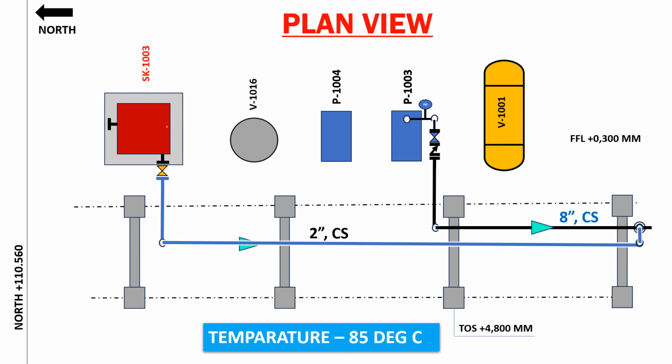The equipment is a bigger unit, so it has more weight. It is anchored and fixed. So if the line needs to expand, it only needs to expand in this direction. I will mark it over here. If the line expands in this direction, then this length will be extended up to here. Then what about this length? If this line needs to expand, it has to expand in this way, because here you cannot expand. But still, this length will have some flexibility, so it will give some backward reaction as well. However, logically, the line has to expand over here. So this is the logical understanding.